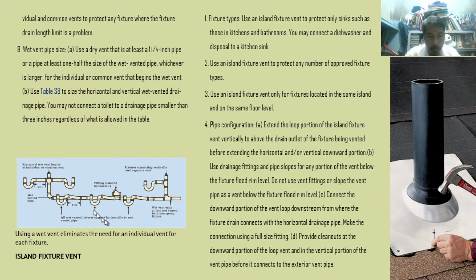Island fixture vent. So there is an island. Use an island fixture vent to protect only sinks such as those in the kitchen and bathroom. So you may connect a dishwasher and disposal to a kitchen sink.